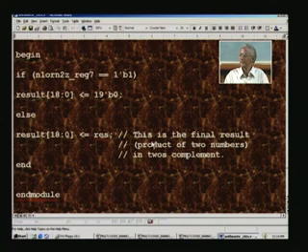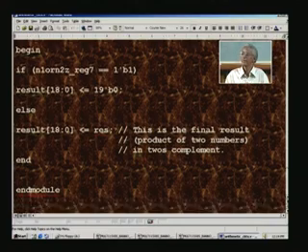This is the final result, product of two numbers in 2's complement. We started with n1 and n2 signed numbers, one was 11 bits and the other was 8 bits. So out comes 11 plus 8, 19 bits, that is what is here, and 18 is the sign bit here. And this completes the design of the multiplier.